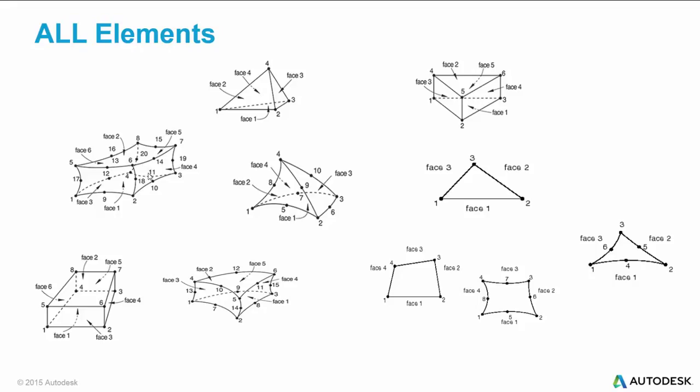So when you run the structural simulation, Helius PFA knows where all of these crazy little points are. It goes and queries what the fiber orientations, material properties, residual strain should be from the Moldflow model, and then we feed that back to the structural model in addition to any non-linearity or linearity that occurs, which is really great because that means that you get more accuracy and more efficiency in your structural simulation. It's way more robust, and we've kind of separated the two processes out for you.